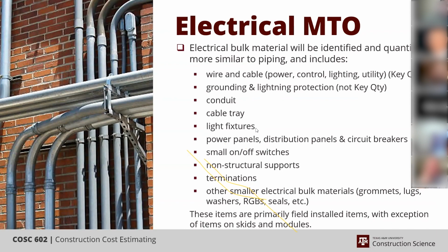A couple other items, and that is your lighting. Your lighting is going to be running in a separate set of conduit. So again, it's 120 volt, so it's not going to be running in the same conduit and likely not even in the same tray as the 600 volt and higher cables. And then those cables will be separated if there's a great enough difference as well. But the lighting fixtures are running on their own set of circuits, and the panels are separated.